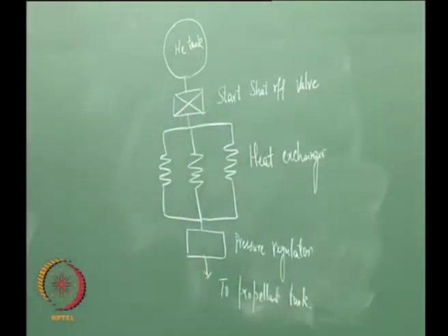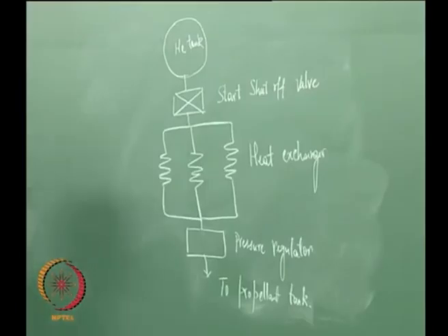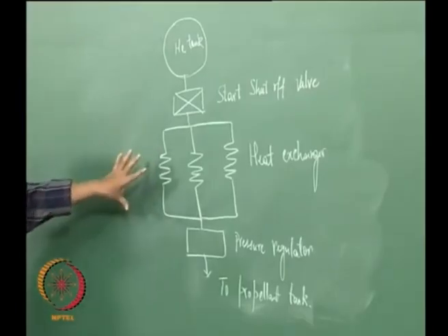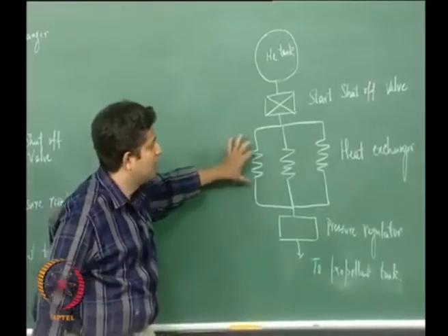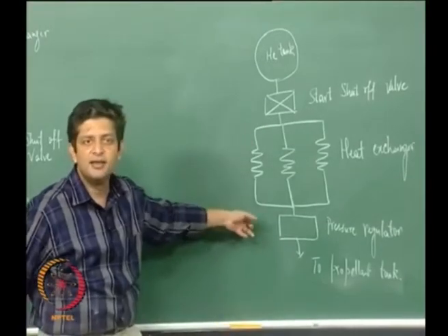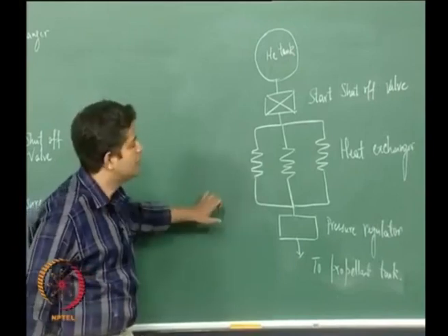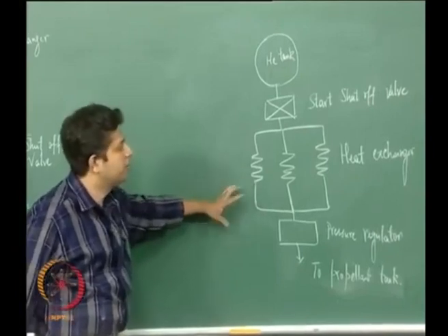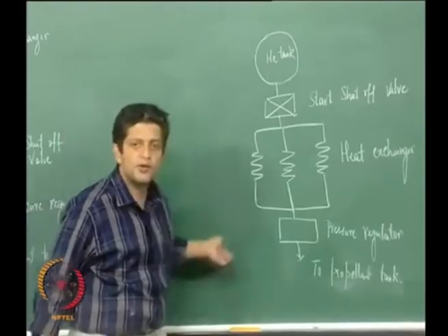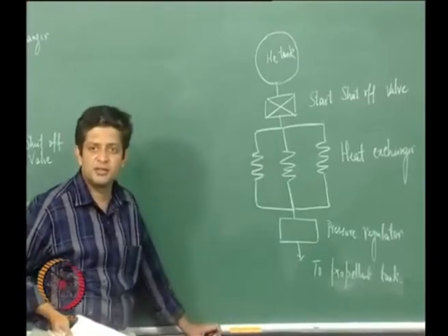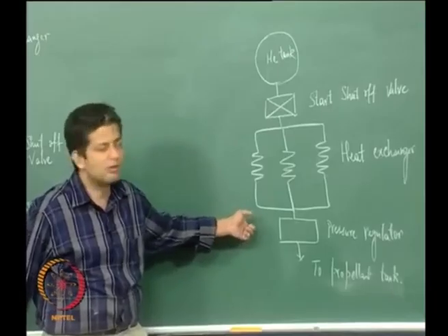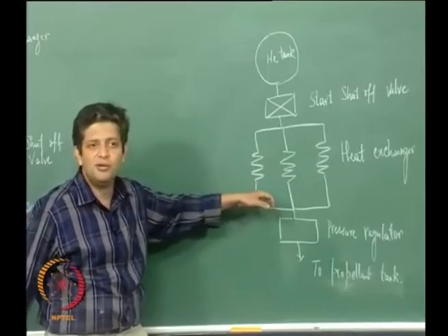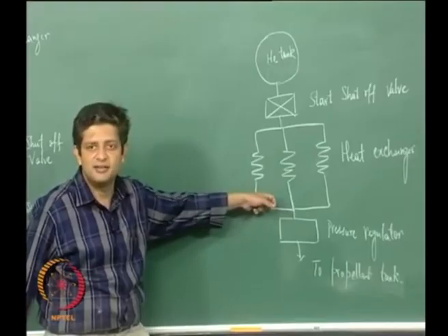Okay. In this design you are not really looking at tampering with the helium tank itself, but using the concept of heating the gas in another way, right. Here you could even contemplate using a part of the exhaust, part of the combustion chamber gases could be bled to have this heat exchanger, right.